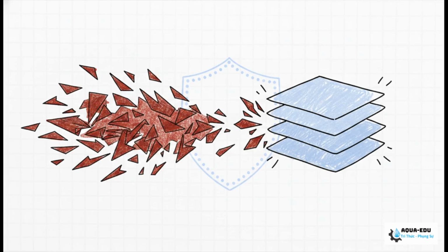Are you operating without a mix bed or MB guard? If you're missing an upstream polishing guard to buffer the EDI from sudden ionic spikes, your highly sensitive EDI membranes are just sitting there taking the full direct hit of any upstream upset.